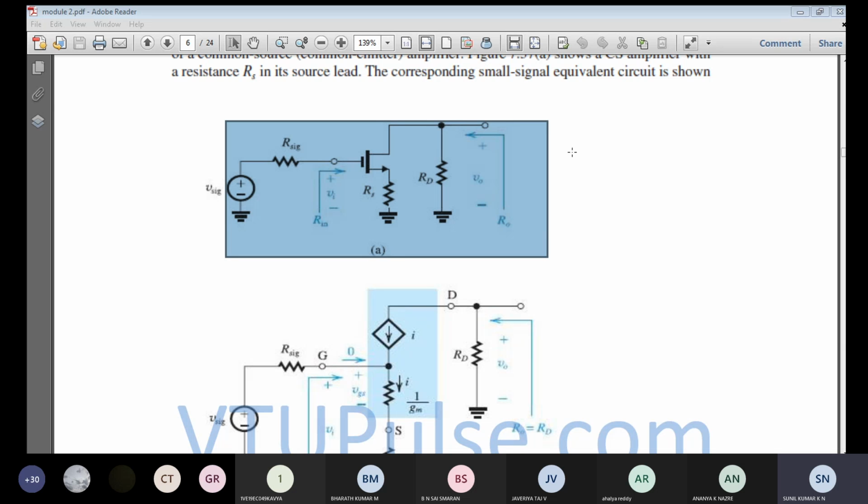So I am going to modify from this model to the next model. By connecting that node X point to the gate terminal, such a way that I am not going to vary any terminal current characteristics. There is no change in the terminal characteristics. So Ig is again the same as the previous value. So Ig is equal to 0.